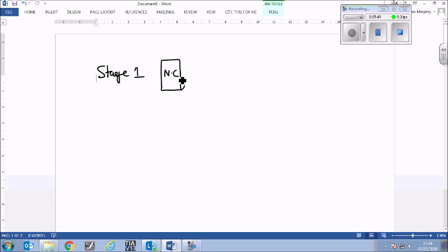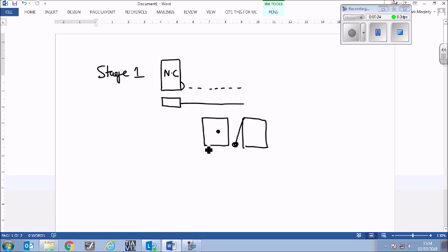Just your normally closed diffuse sensor, which shines the beam of light across. You then have the barrier itself, and that would lift up out of the way. We've got our inductive sensor, which is on the ground, which is the wee blue button, and then you've got your sort of roller switch that sits off to one side, if you remember the car park. And a dreadfully drawn car is about to appear. Just going to be a square box, that's all.